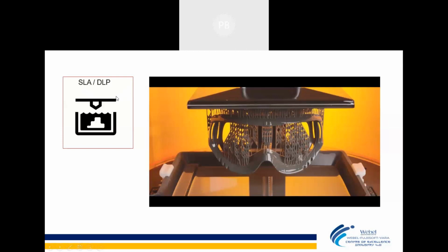But yes, SLA printers are smaller in size. You can't print very long products, maybe half a meter or 1 meter products, in SLA, because with this liquid the build volume is a limitation for SLA technology. But yes, SLA is again a very fast technology as compared with FDM. SLA is like 100% faster than that, a very fast technology.